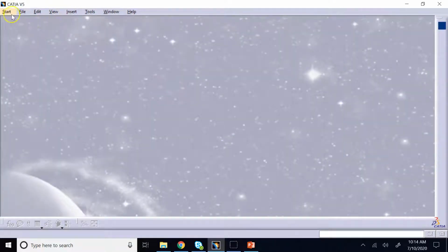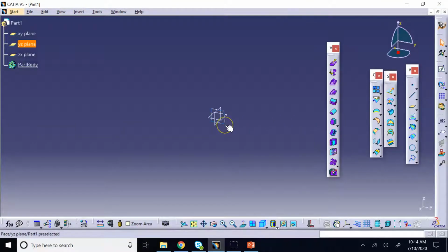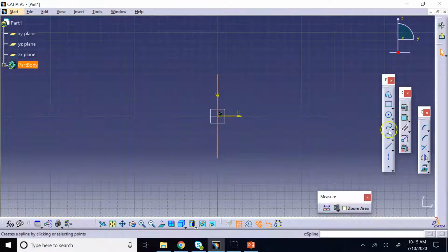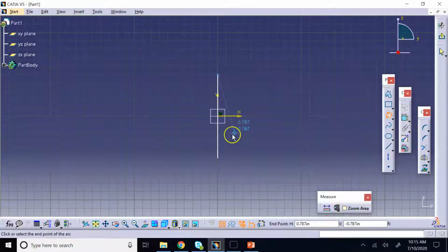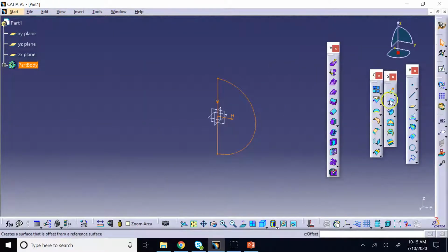So we go back here. So as I said, you can draw any surface that you want. Let's say you want a spherical surface, right? Like a ball. So if you go to any of these planes, all you need to do is to draw a semicircle. So here I draw a semicircle for you with the line and then the 3-point arc, like that. Then I get out, and then you use the revolve command here, which is under extrude.